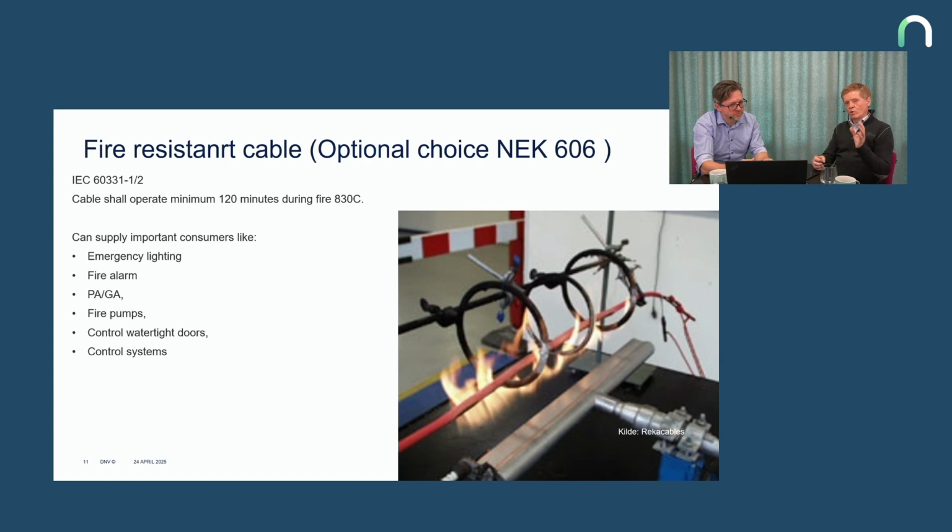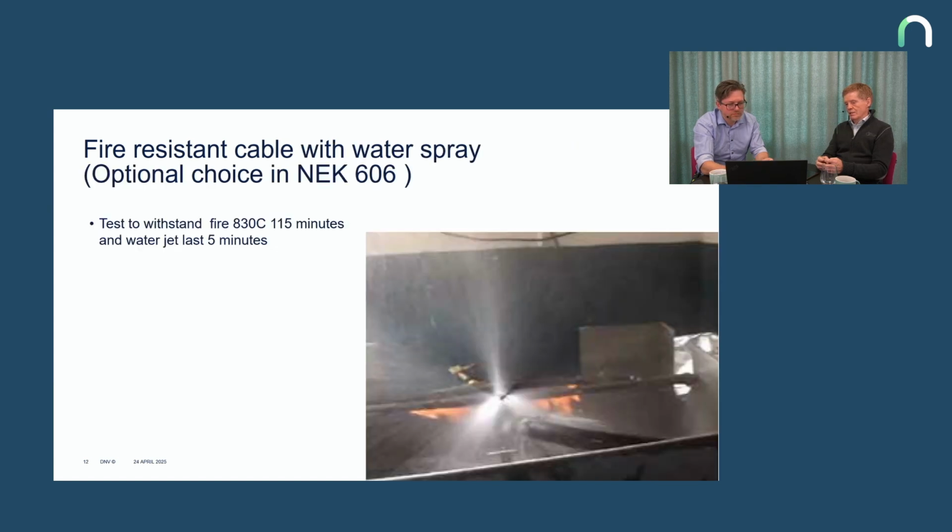But if there are firefighting efforts and you put a fire hose and spray this with water, a normal cable will just break because of the water. But in that case, as we can see in the next slide, there is an additional test where you have the water spray. And these cables are tested in the last 5 minutes of the 2 hour period.